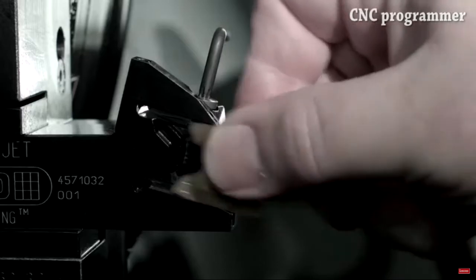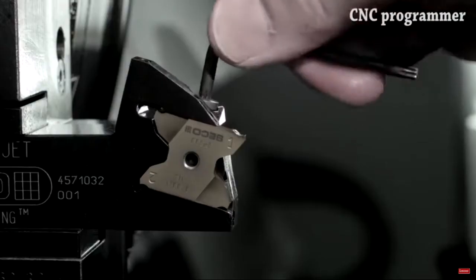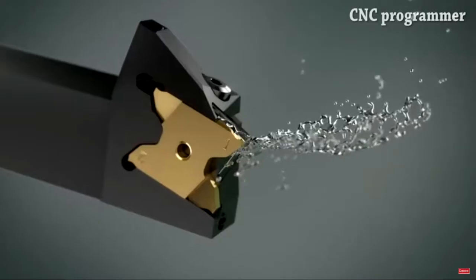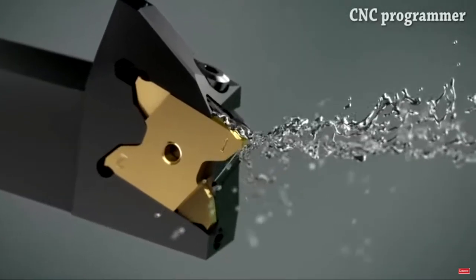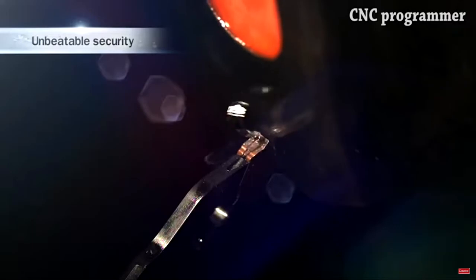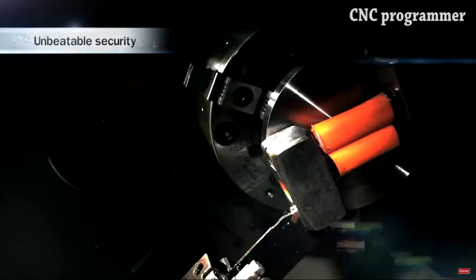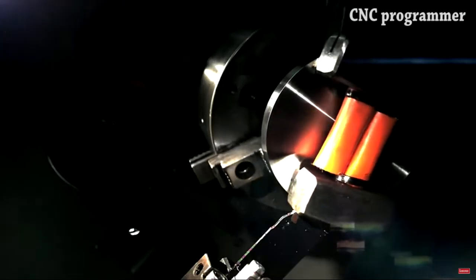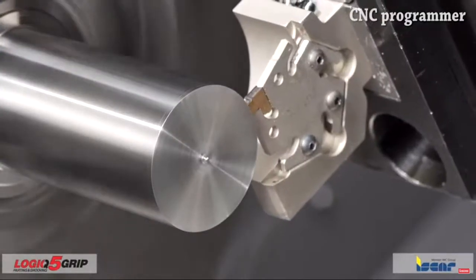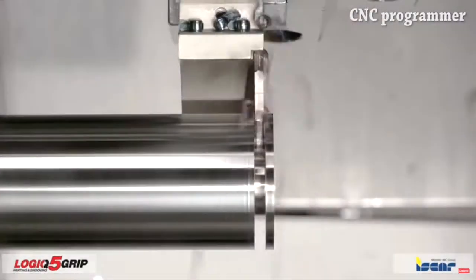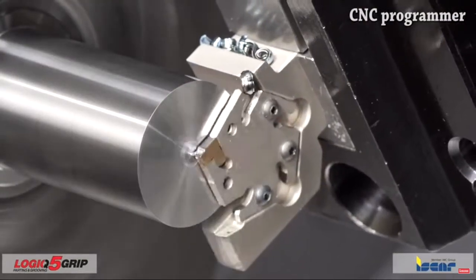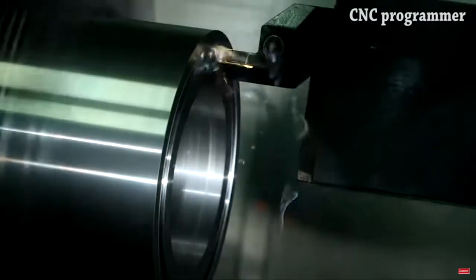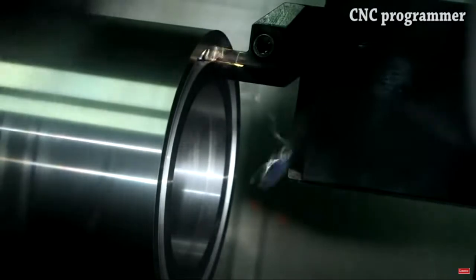Now let's take a look at a traditional insert cutting tool. This one could only cut smaller diameters, but it's a carbide insert, and oftentimes coolant is designed to go through the cutter. And so the very tip cuts as it goes through the material, as you see in the slow motion. Here's an example of a cutoff tool. Here's an example of a face grooving tool. It's grooving in the face of the bar.